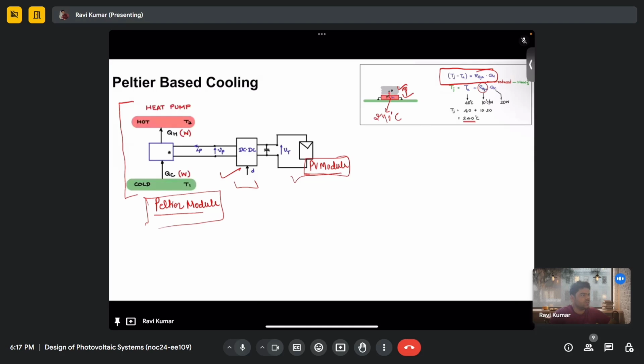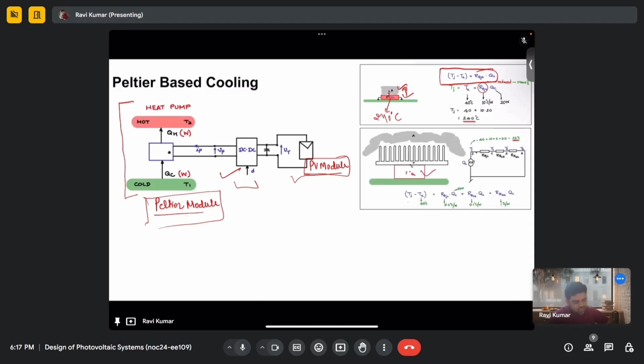Using some fins or some other material. Usually what we have over the NIC is these aluminum fins. Those increase the area and help in dissipating the heat. Similarly, we can have this IC with these fins and an atmosphere. In this condition, if we calculate the possible minimum Tj temperature, it is around 72 degrees Celsius. So it is a large drop from 240 degrees Celsius to 72, and it is without using